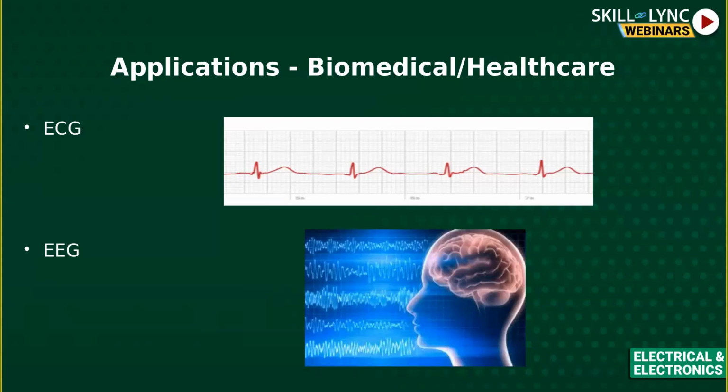Now, I'm sure you must have heard about ECG signals before, but did you also know that our brain emits something called EEG waves or electroencephalogram waves? And if you try to tap the voltages appearing on the scalp of your head at different locations, and that can be done with a few electrodes. By doing that, you can actually make out what your brain is thinking. Isn't it interesting? Now, these electrodes are mounted in a cap-like frame that can measure small signals that appear on your scalp, something in the range of 50 to 60 microvolts, which is a very small signal.